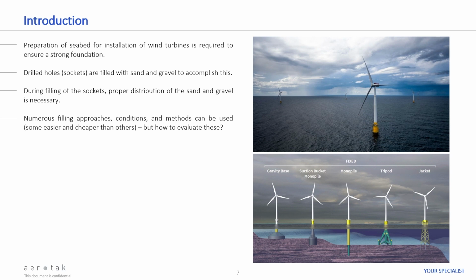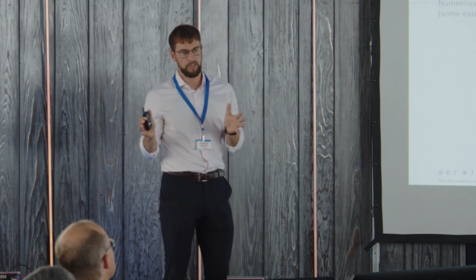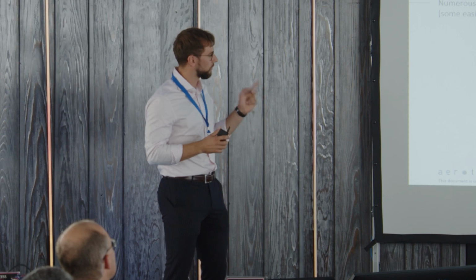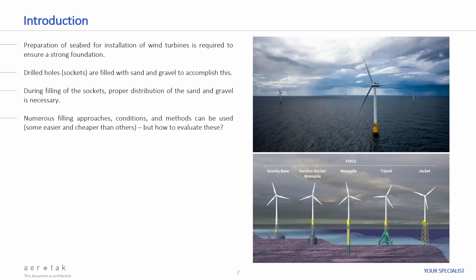So the customer is a Danish company that specializes in transporting sand from one place to another. And that can be used in a lot of different means or in a lot of different processes. But what they're using it for in this specific case is to fill up socket holes in the seabed with sand and gravel, because you need to prepare the foundation if you're putting a monopile structure on it. So for example, let's take a wind turbine tower, if you have a gravity-based structure that needs to be just placed on the seabed, or this type of tripod structure, then you need to make sure that you have a proper foundation so that there's nothing moving around there.